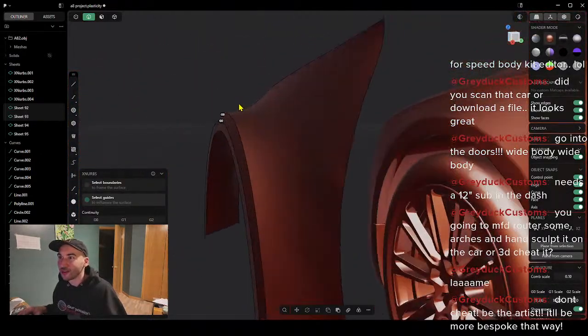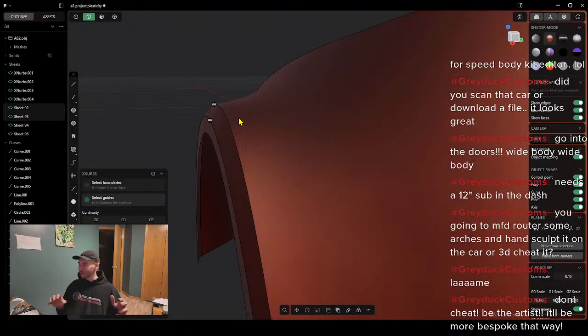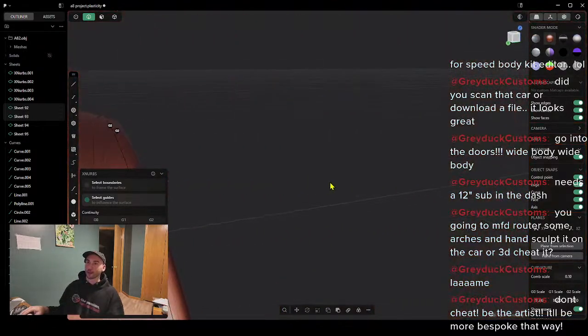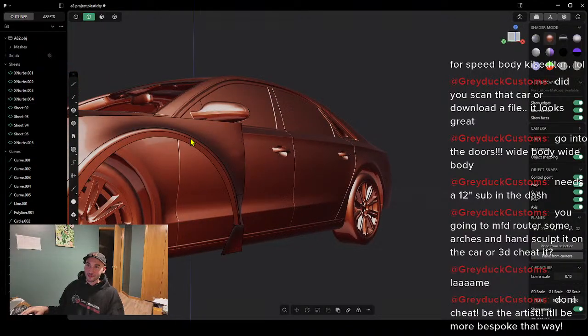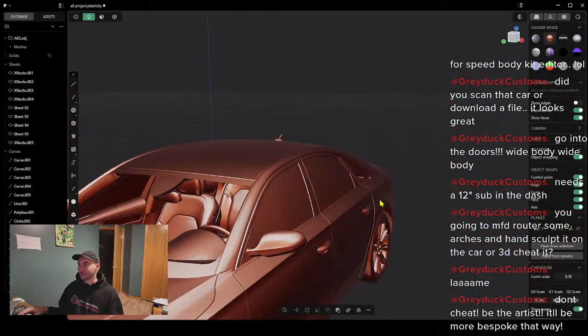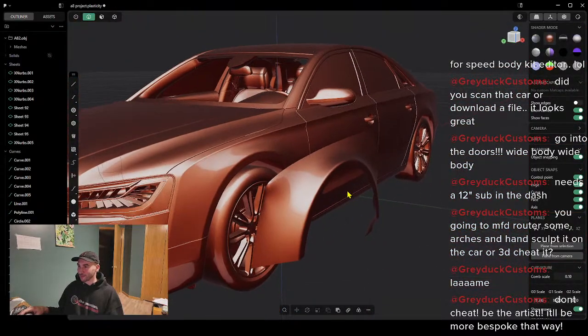So that's G0 continuity, which is just a perfect flat bridge, but I should be able to do a G2 continuity, which should smooth it out. There we go. So there you got that kind of nice smooth ridge there. Everybody likes that. And if we hide the lines, you see exactly what we're talking about. So there's a nice smooth curve there.